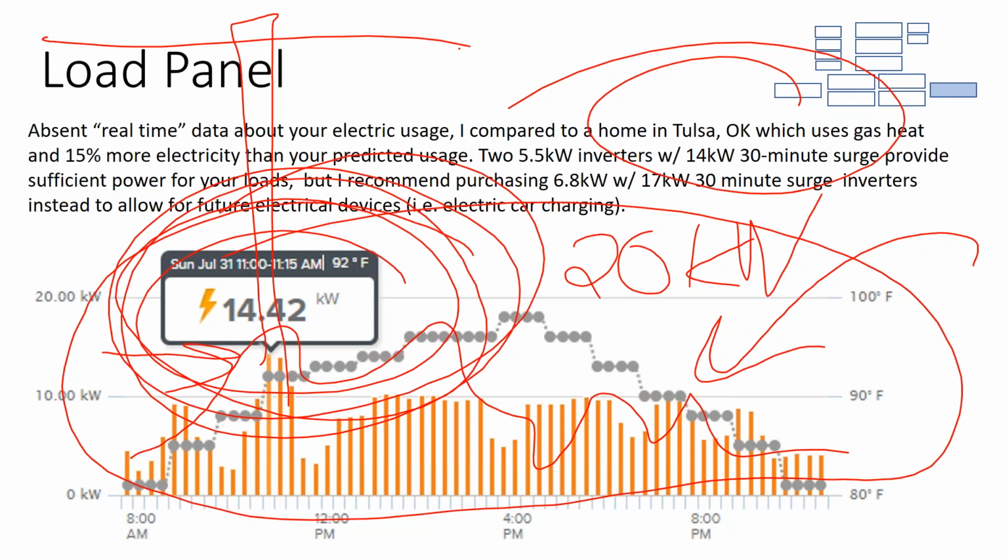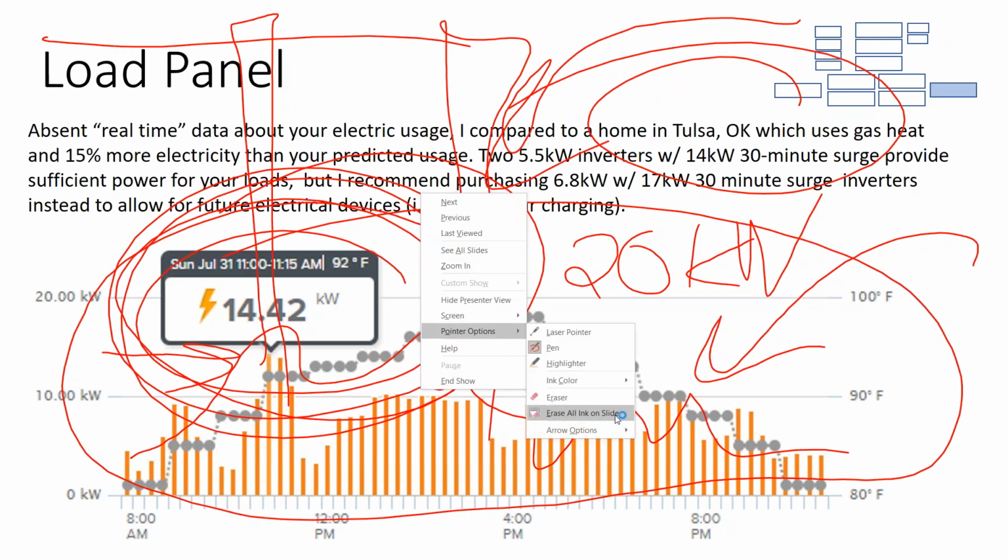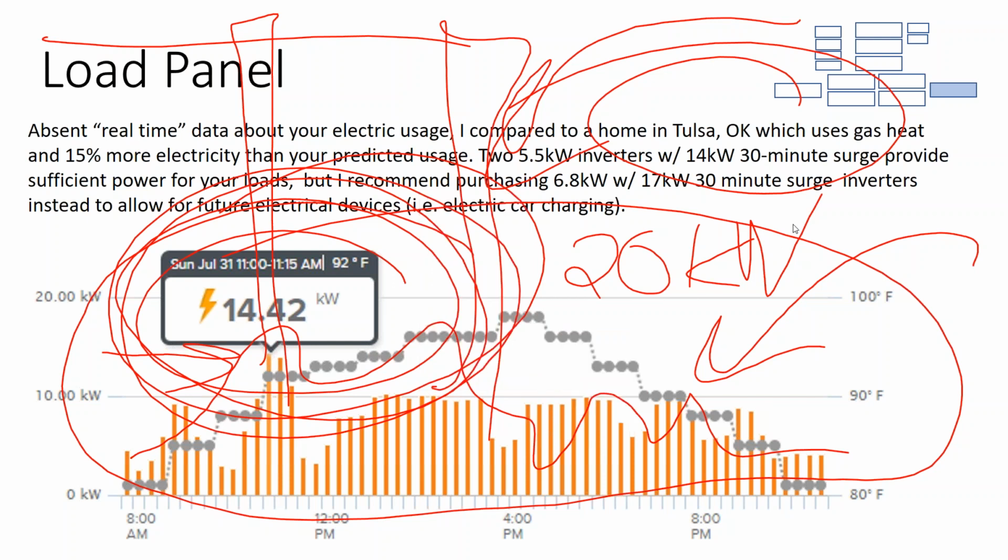If you do have those higher loads, then you want to use them in the middle of the day when your solar array is providing most of the power, so that power doesn't come out of your battery bank. So you could, in theory, have a tankless water heater on an off-grid system that is simply there to heat water rapidly during the day when you have excess power available. Although a tank electric water heater can do the same thing.